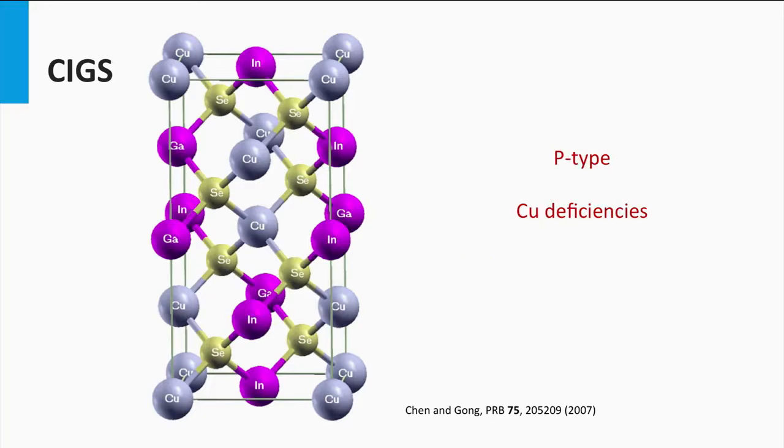The CIGS absorber layer is a p-doped layer. The doping is a result of intrinsic defects in the material related to copper deficiencies. These vacancies efficiently act as an acceptor. It means electrons excited from the valence band can get easily trapped. As a result, the holes become the majority charge carrier density.